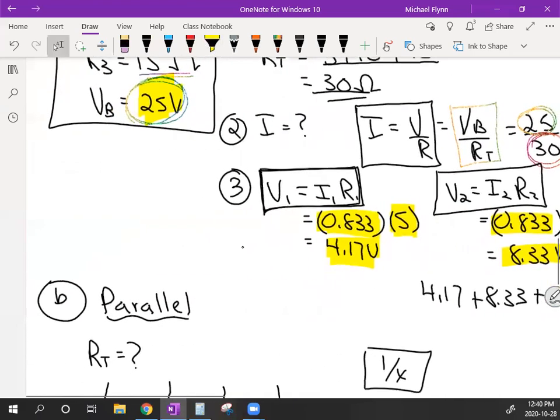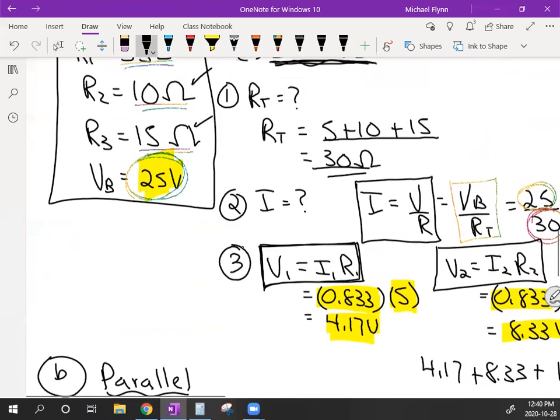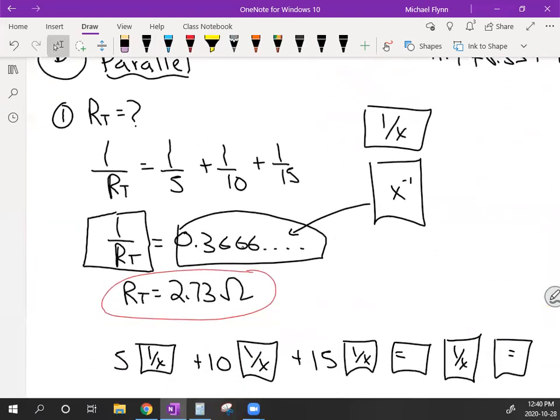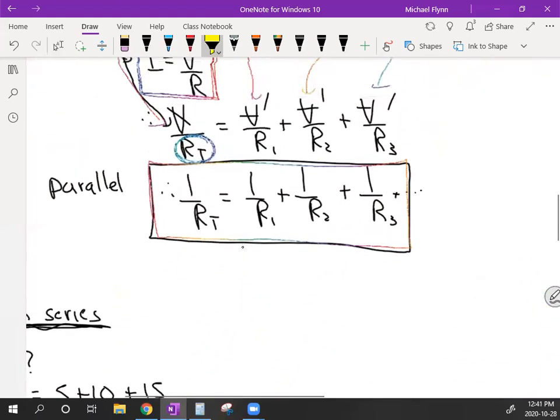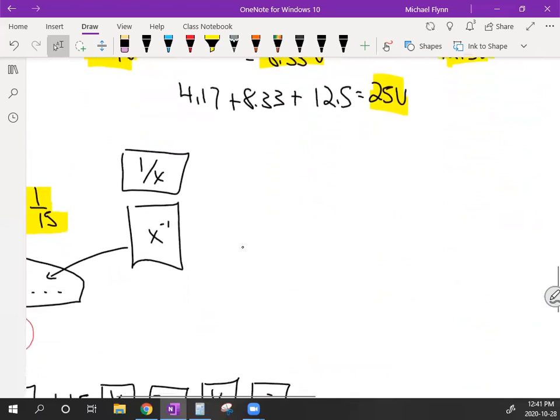All right, now let's do the same thing, except we're going to do it in the parallel circuit. In a parallel circuit, we're going to connect the same three devices plus the same battery together. But when you find the total resistance in step one, you have to use the reciprocal equation, because that's how it works in a parallel circuit. And remember, we did that up here. This is your parallel circuit resistance right here. So we have to use that form of the total resistance equation.